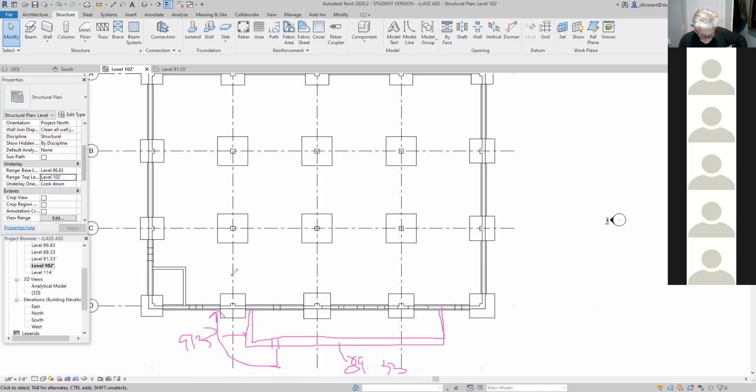You can look at GG, or you can even look at the elevation EE. It tells you the wall is 6 inches below elevation 102. So that's what we were figuring out. All I'm saying is that that information is in a number of places. As long as the information is correct in all the locations, then it's correct. So now I'm going to erase this, clear this drawing.